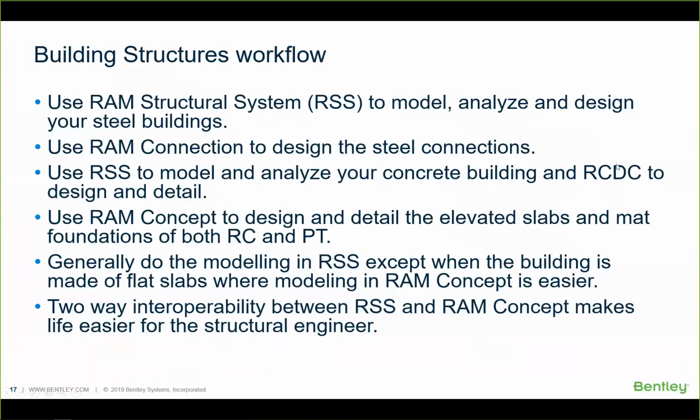And RCDC doesn't support certain codes like the Australian code and New Zealand code, whereas RAM Concept supports the Australian code. And RCDC is suitable for one-way and two-way slabs only, whereas RAM Concept is suitable for even flat slabs as well as post-tension slabs with openings also. Okay. And long-term deflection calculations can be done in RAM Concept, whereas RCDC does not calculate the long-term deflections. Okay, so there is some overlap, but RCDC does many other things like beam design, column design, as well as detailing, bar bending schedule also, as well as estimation.